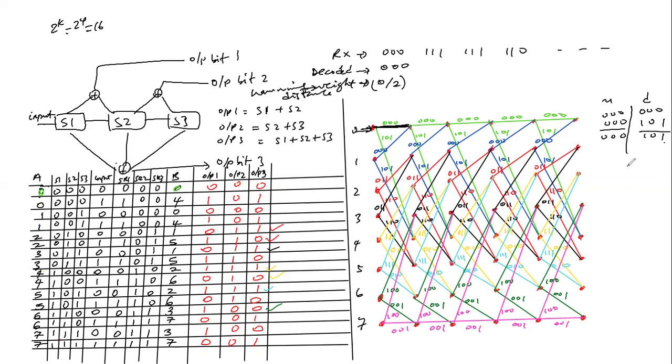Then the next part is to check 111, 111, 111. From this point, it's either we go upward, which is 0, 0, 0, and we check the Hamming distance, or it comes down 101, 101. So this is 111, and then this is 0, 1, 0. So the weight here is 3, 1. So it's 3 over 1.